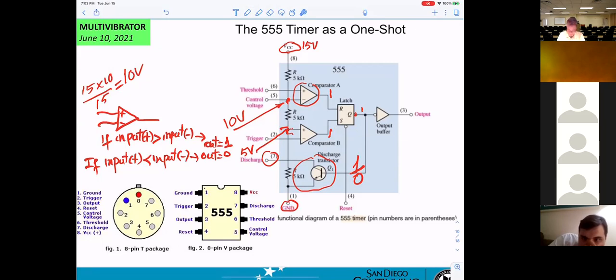That means you can see that pin will be discharged, charging, discharging. That means when you connect into the circuitry, they connect to capacitor. Capacitor charging or discharging. Okay? When they charging, Q1 must be off. When they discharge, Q1 will be on, so they connect to the ground, they will be discharged. That's how they work.